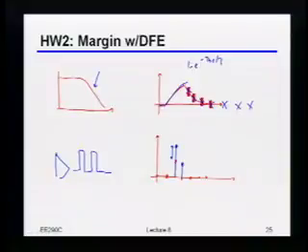So that loss, unfortunately, you can't get rid of with the DFE, right? All the DFE does is kill all of the taps afterwards so that they don't interact with each other. But you still end up with this loss here, okay? So it's just another way of saying that the DFE is a clever way of giving you a channel that basically looks flat, but it can't really get rid of the loss. It's better than a linear equalizer, but it still can't get rid of the fundamental loss that you take on that one initial bit. Does that make sense to everybody?